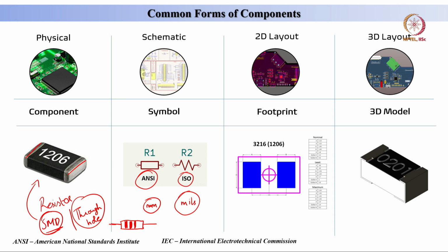So the dimensions remain the same, so that when you give it to a PCB vendor, they can make the pads for soldering the resistors just like you intended. So usually we use components. When it is translated to the footprint, we just use the pads or the places where we need to solder the component. We do not actually represent the component itself, but just the footprint of the component, as the name suggests. We just represent the places where they need to be soldered.